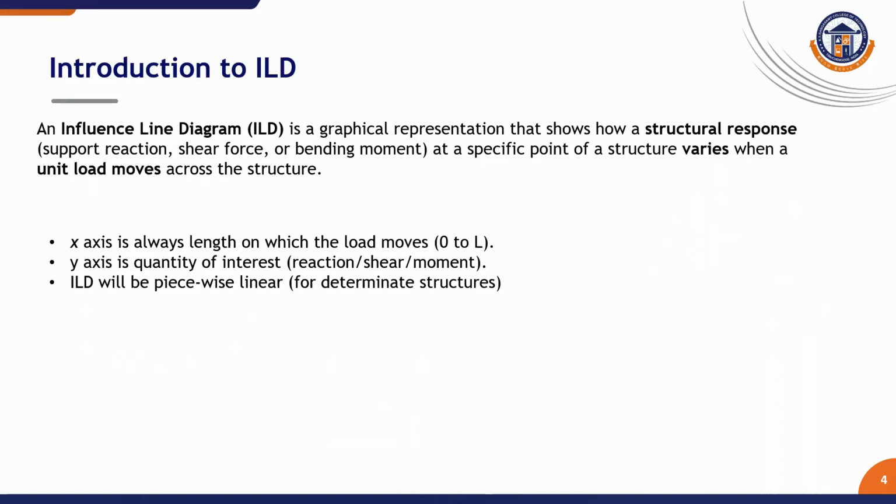The y-axis represents the magnitude of the structural response we are interested in, whether it is the reaction at support A, the shear at section C, or the moment at point B. A key characteristic, which will be explored later, is that of statically determinate structures, which are our primary focus today. These diagrams are composed of straight line segments, making them relatively straightforward to construct.